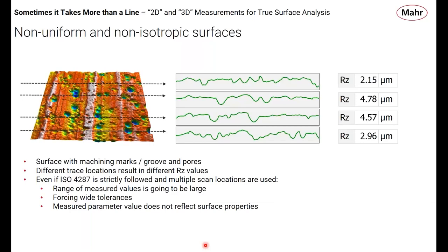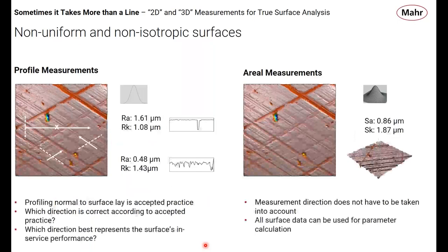So in this case, even though when making those profiles, we can absolutely adhere to ISO 4288 to the letter, we can do it. But the problem is we can't quite determine whether we're looking at grind marks or pores, or which we want to do. It's not optimal. I talk a little bit about the tolerances and the ranges there, but that's another discussion. We'll skip that for now. The point here is that we can't distinguish pores from grind marks, but we can do that later.